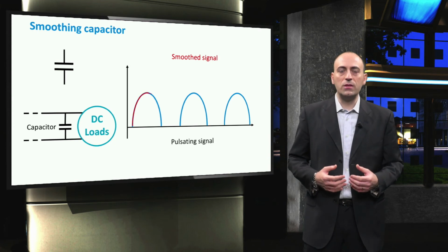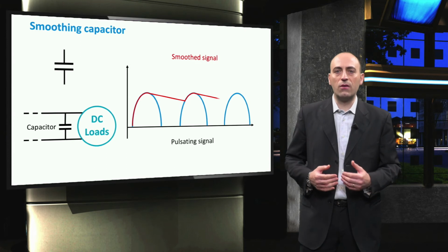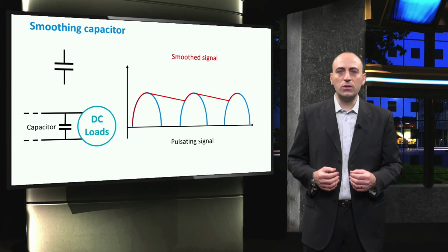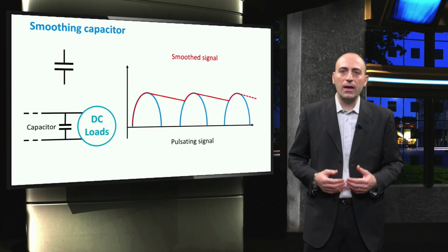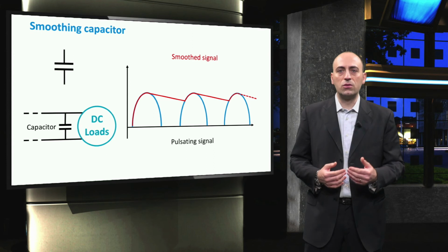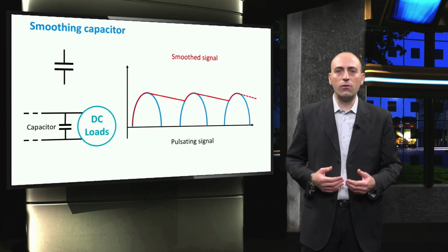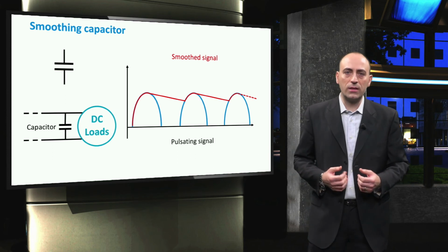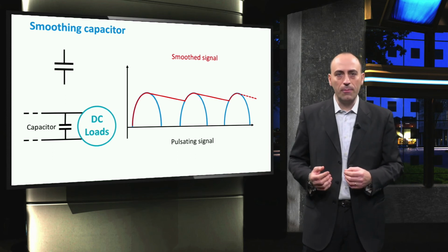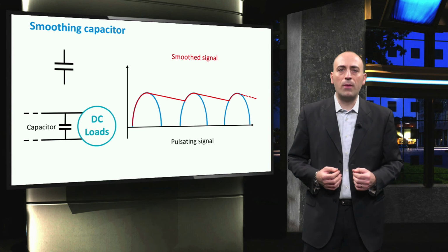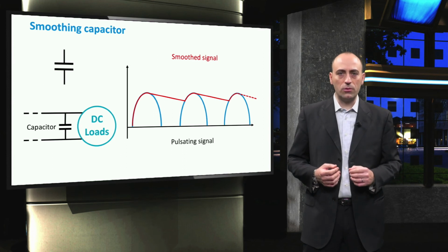As the voltage of the signal increases, it charges the capacitor and also supplies current to the load. When it reaches the peak of the signal, the capacitor is charged to its peak value, and here the role of the capacitor is evident because it starts to release the stored energy. So in this short gap of time, the continuous flow of current gradually moves to the next periodic pulse, filling the gap and allowing the load to be powered at all times without any interruption.